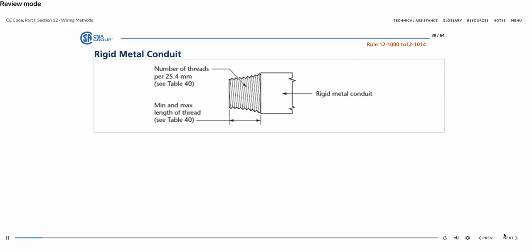Rigid conduit is one of the most rugged and durable raceways used in electrical installations. Manufactured of thick wall steel or aluminum, rigid installations provide a high degree of mechanical protection, good electrical continuity for a bonding path throughout the length of the conduit, and an overall solid installation. Rigid will often be used in industrial areas subject to mechanical injury, hazardous locations, and outdoors, in environments where PVC is not suitable.